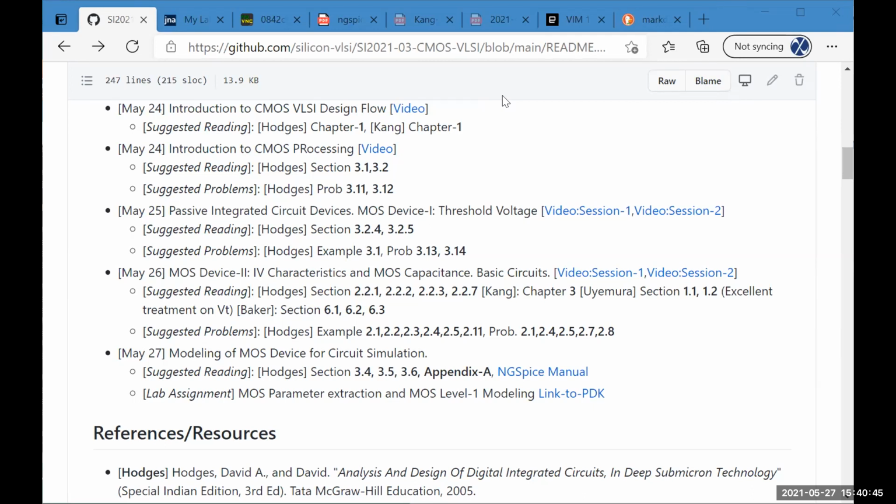So that's one thing I just wanted to point out: just because it's in the model file doesn't mean you can't pass it. It depends on the simulator, but most simulators will allow you to overwrite it. The precedence is basically, if you don't assign the numbers, then it falls back to the default number, which I showed you in that BSIM manual.